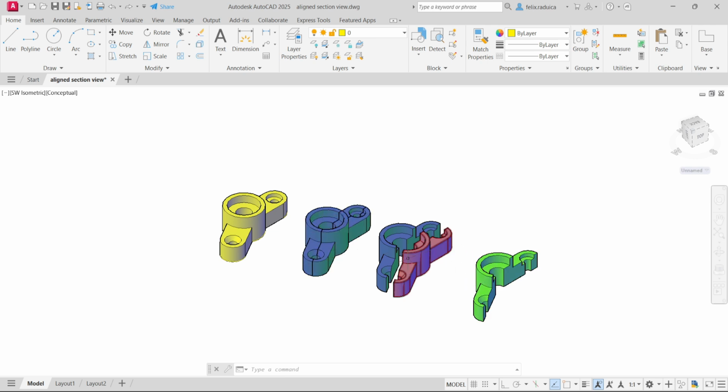And we remove one of the halves of the part, and the other half we consider for projection in the front view. While in the top view, we'll consider this projection from this direction, and we'll have to create a trace for the cutting planes as well.